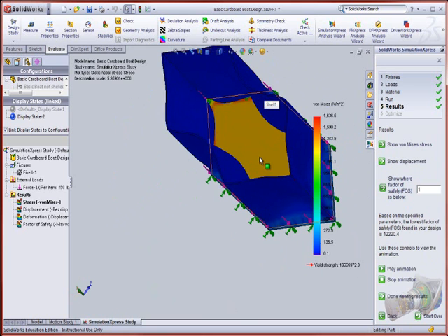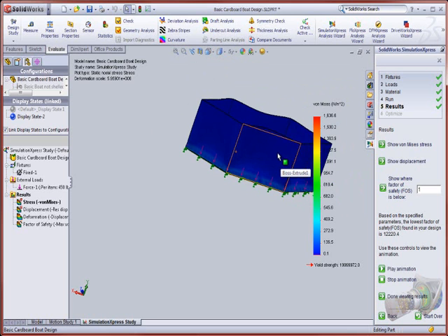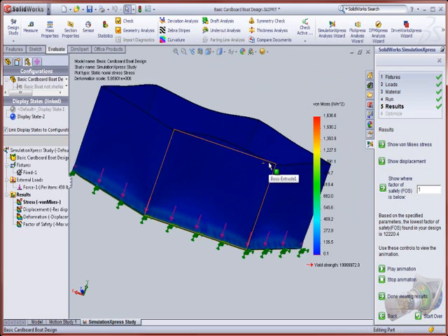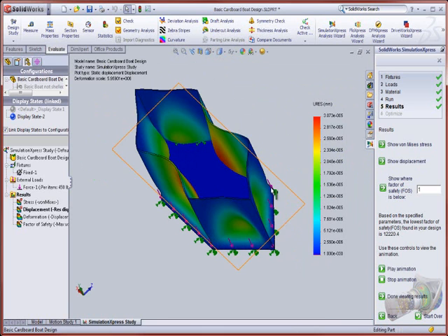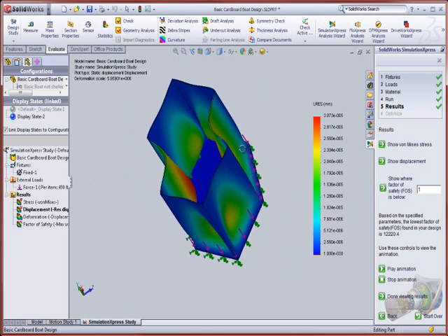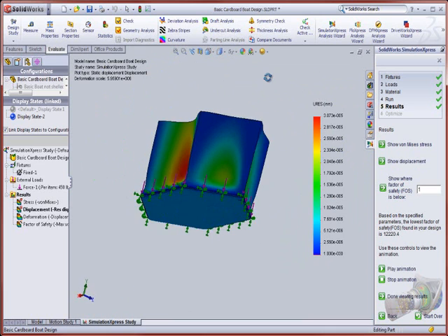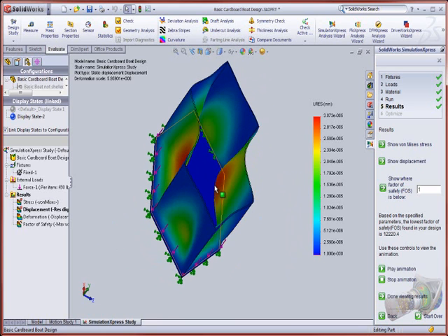And if you watch a lot of the boats in the videos on the SUU website, you'll notice that truly a lot of them actually do kind of cave in on the sides here. Now, I don't know how accurate the actual measurements are, but if anything, it gives you a general idea of your design and where your problems are. So what I'm looking at right here, I would say it's probably going to be a good idea to come back in here and put a stiffener. And it looks like maybe the stiffener might be better off down at the bottom, or maybe put one at the top and one at the bottom.